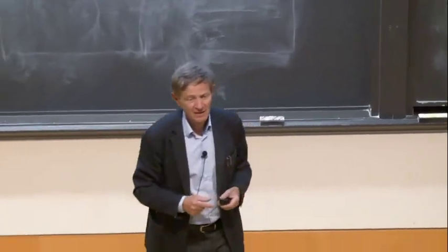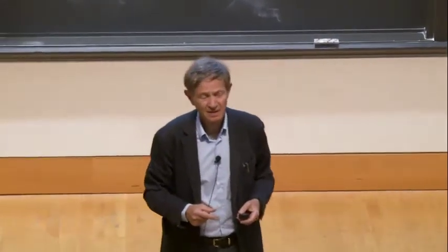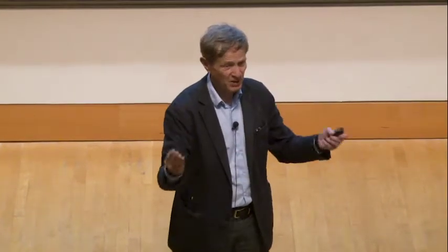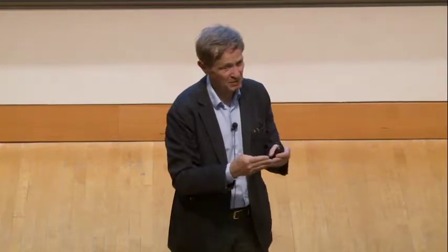Yes? So the Rayleigh criterion accounts for coupling between acoustic fluctuations and heat release fluctuations. Should there be something to account for velocity fluctuations as well? No. Now, you have perturbations of everything. Velocity, the equivalence ratio can fluctuate, other things can fluctuate. But basically, the two main perturbations for flames are the velocity fluctuations and the equivalence ratio fluctuations.